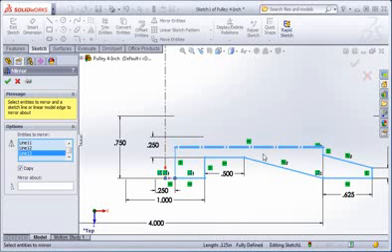Highlight it, and you should see it highlighted in the graphics area. We don't need to mirror this line, so type the delete key. This deletes the line from the list. If you leave the copy option checked, the lines will be copied above the construction line, which is what we want to do. If you uncheck the option, the mirrored lines will be created above the construction line, but the existing lines will be deleted. You might want to practice unchecking this option later. For now, leave it checked.